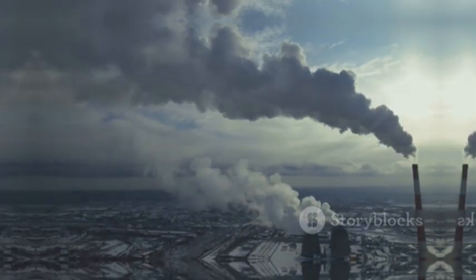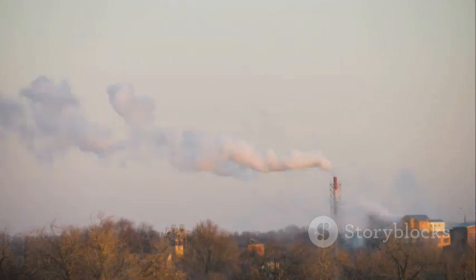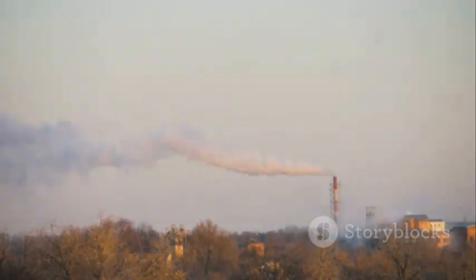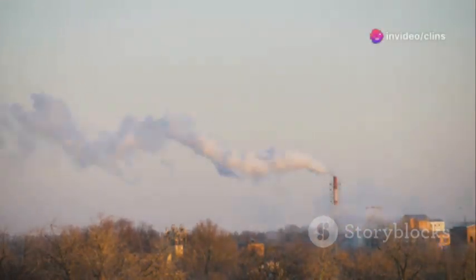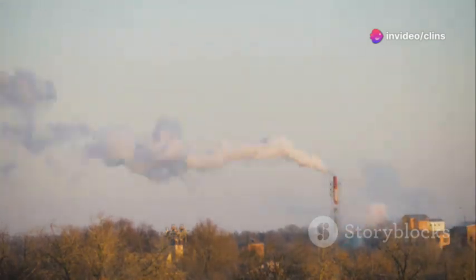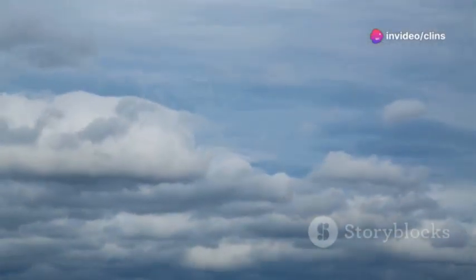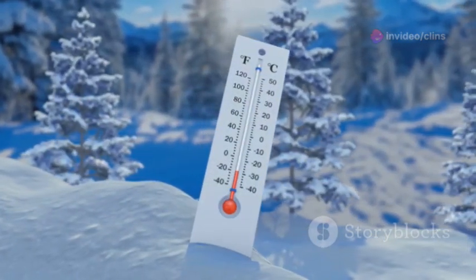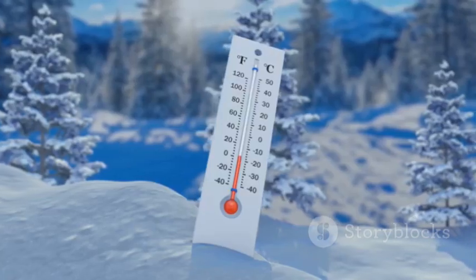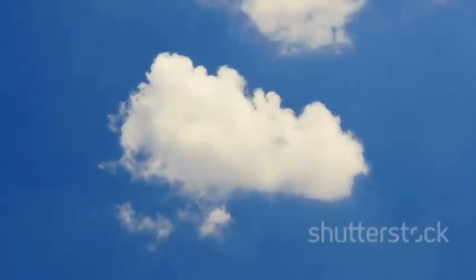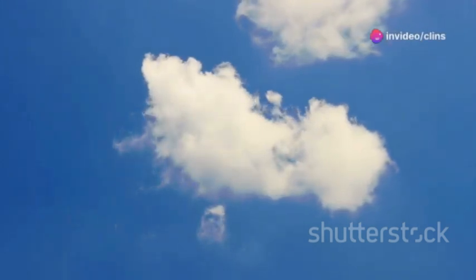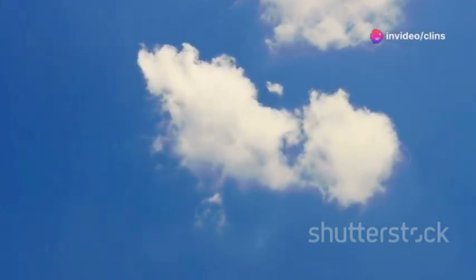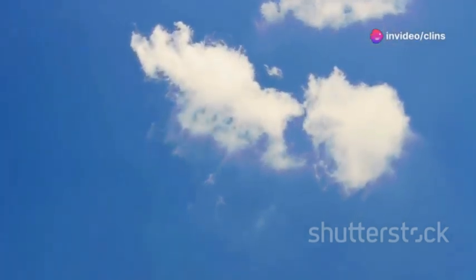Dispersion of air pollutants. Let's start with the mixing height or depth, which refers to the vertical extent of the atmosphere in which pollutants can be dispersed and diluted. Then we have lapse rates. The environmental lapse rate is the rate at which temperature decreases with altitude. On the other hand, the adiabatic lapse rate is the rate of temperature change of a parcel of air as it moves up or down without exchanging heat with its surroundings.